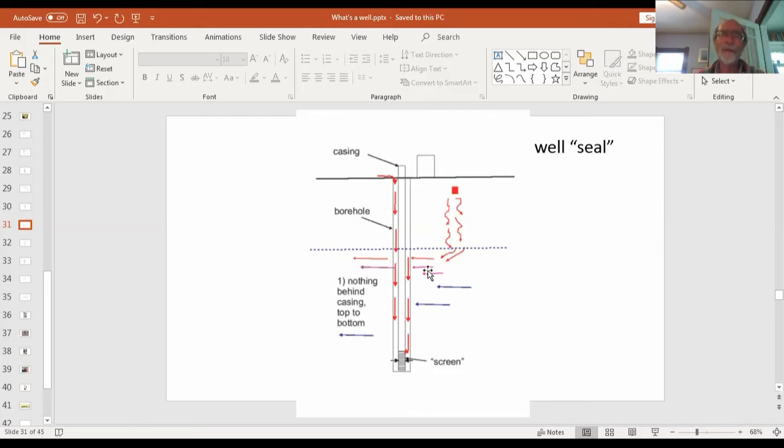Well, what that means is, yes, the way the well was completed allows easier passage of surface-based contaminants, either surface or near subsurface, to find their way either directly down the well, or in this case, even if I've just contaminated the top of the aquifer, remember I'm sucking water out here, so it's going to want to come into the well and go down and come back out my well. So this is the poorest well completion, and there are plenty of those out there.